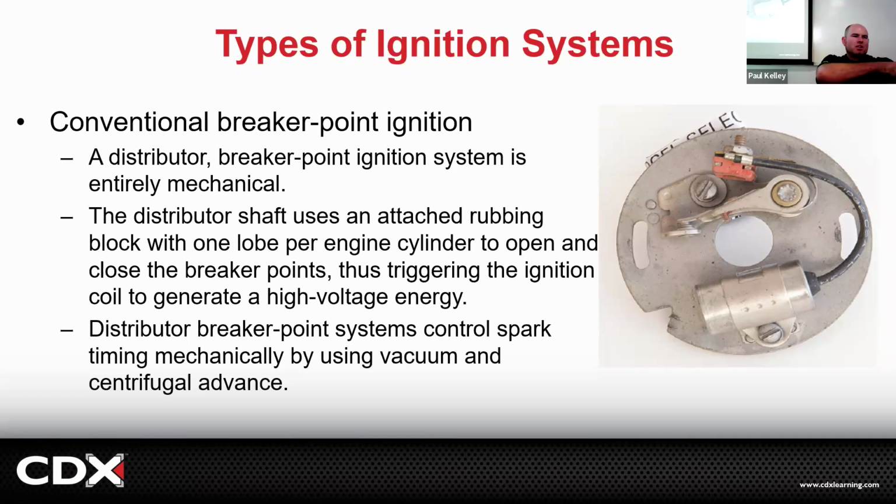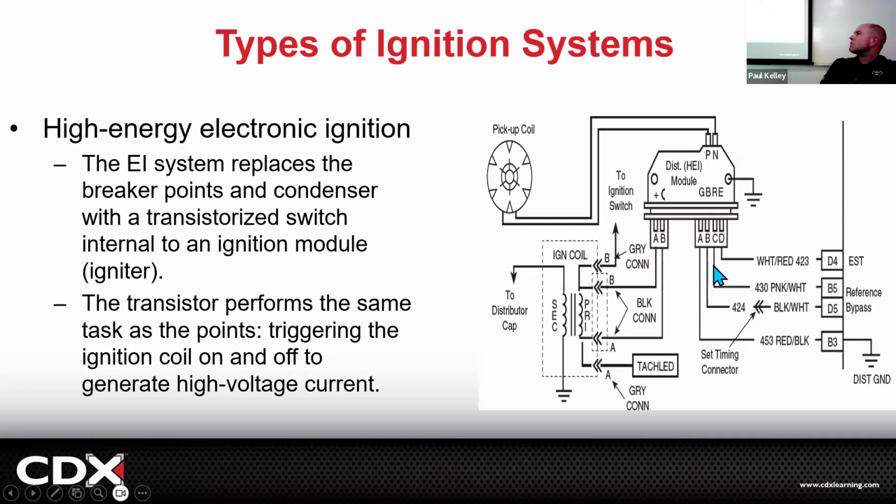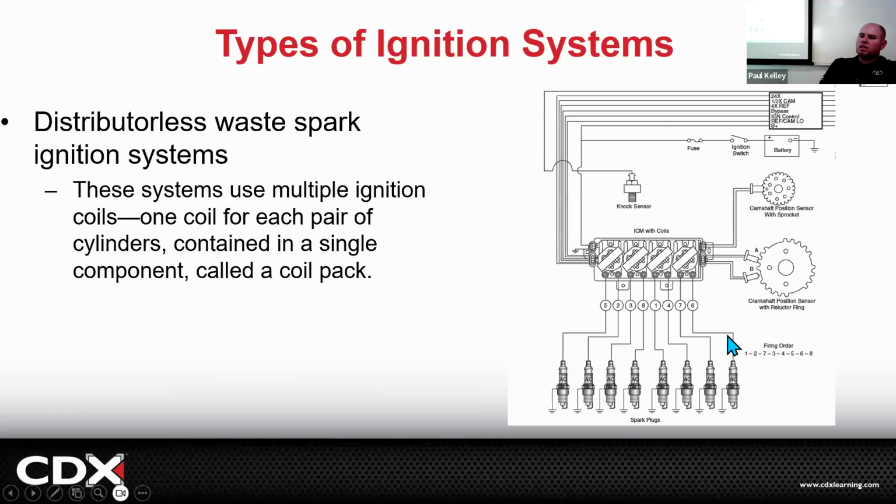Like it was the greaser dog stuff, bust out the matchbook and fine tune it a little bit. But we could adjust the base timing by rotating this with a wrench and a timing light. That's going to be in the service part. Then when we got to this, it could do some of the advance and retard, but not much. Once you're into this, you're almost there.